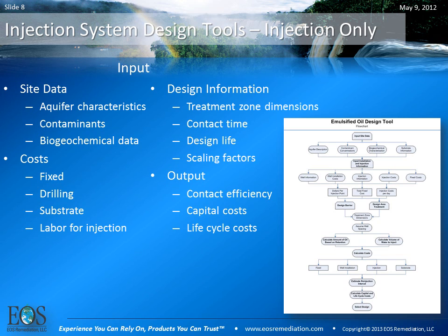You need to consider your costs. What are your fixed costs, your drilling costs, your substrate costs, your labor for injection. All of those play a part and are affected by the way you design your system.